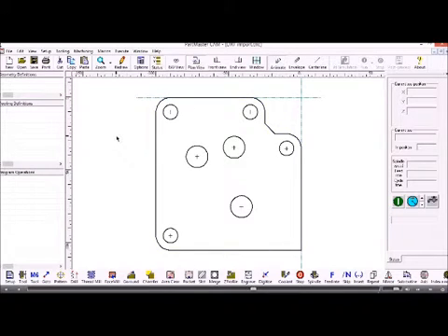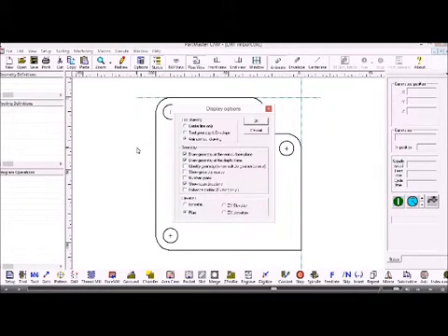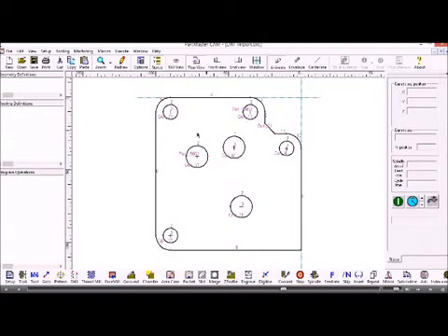The other thing that you might want to do when you're importing a DXF file is identify the geometry and to discover the directions that the contours have been created in. To do that, with the cursor in the drawing area, you right click the mouse and you can say number spans and show geometry names. So when you click OK, then each individual element or a span that goes to make up the contour is labeled. So as you can see, the outside contour is contour number 1 and it's made up of 11 spans.